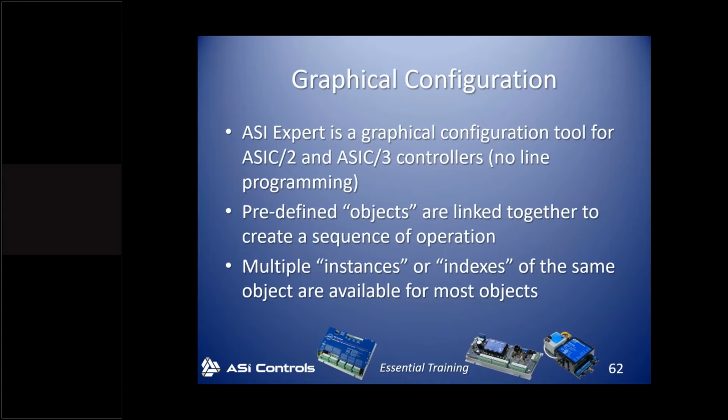And I think I mentioned on Monday that one thing you'll have to get used to for the hardware points is that our objects, when you're programming the controller, start counting from 0. So there are 16 inputs on a 9540, and they start from instance number 0 and go up to instance number 15, which is a little different. Most people would think that they'd be numbered 1 through 16.